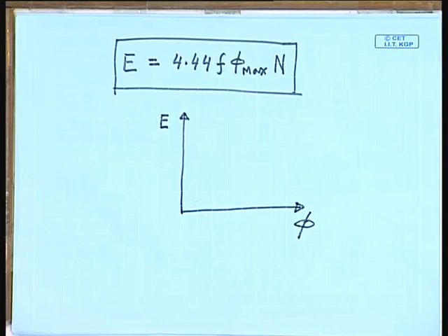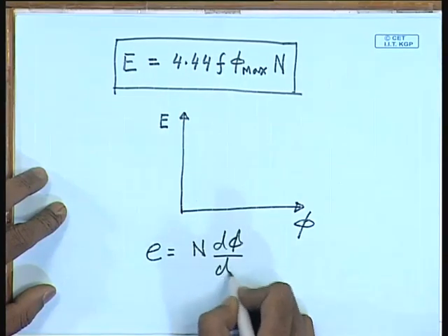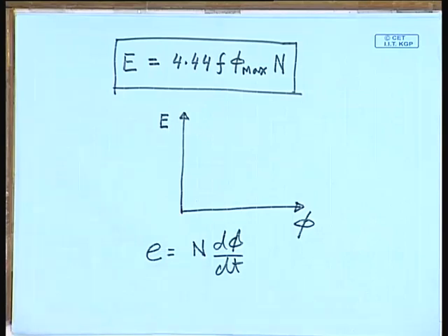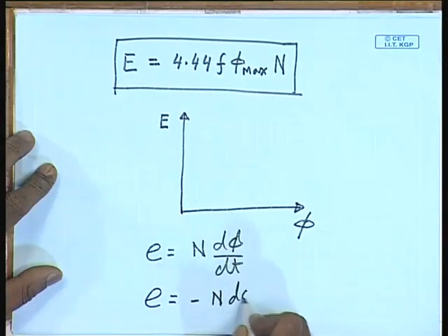The quantity that we have been calling induced voltage is in fact called the counter induced voltage by many authors, because here we have got this E by simply saying E equal to n d phi dt, and we have incorporated the last part of Faraday's law, that is, it opposes the very cause to which it is due, by taking its proper polarity. This many authors call the counter induced voltage. The actual Faraday's law says E equal to minus n d phi dt.